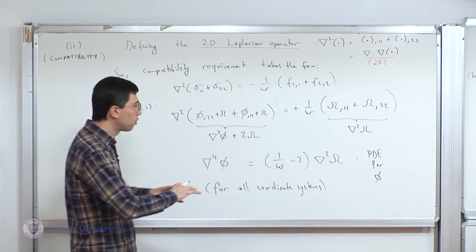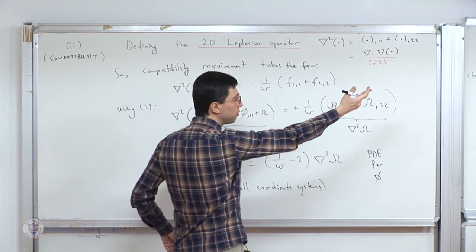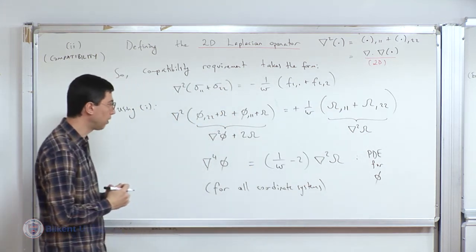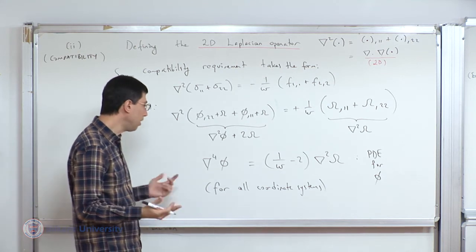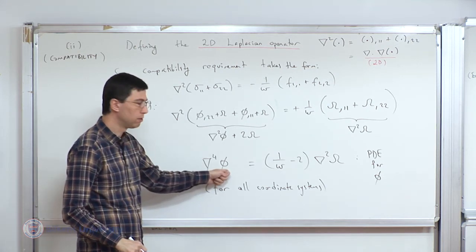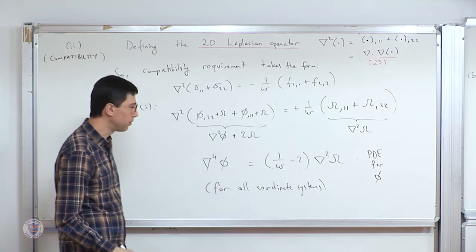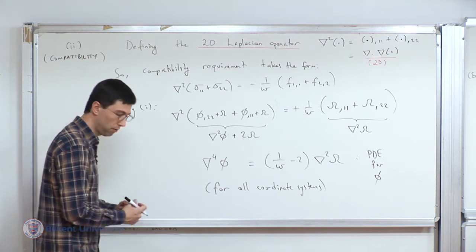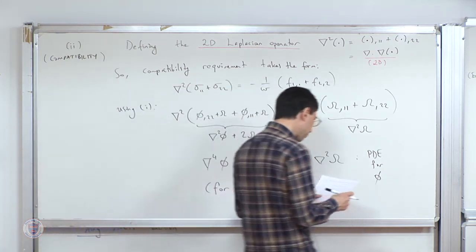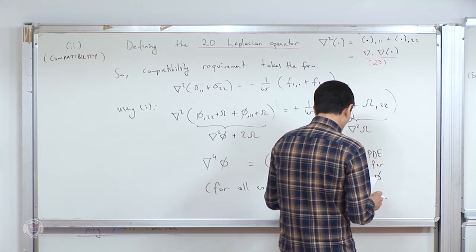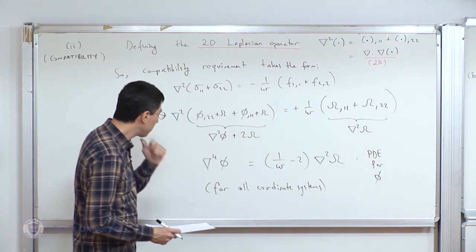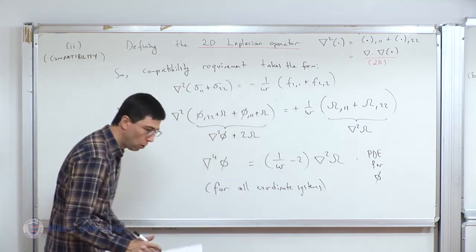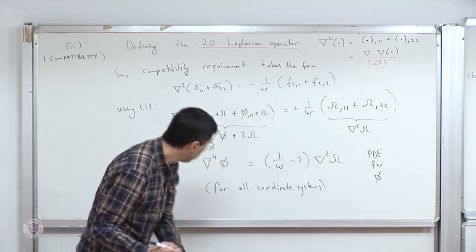So I can propose some form of the Airy stress function. Yes, that's how I calculate the stresses. And yes, equilibrium is satisfied a priori, but not every phi is permissible. Phi has to satisfy this requirement, and that will restrict further the possible form of phi that I can work with. All right. So the right-hand side is clear, right? This is the definition of the Laplacian. So on the left-hand side, let me make a quick note here.